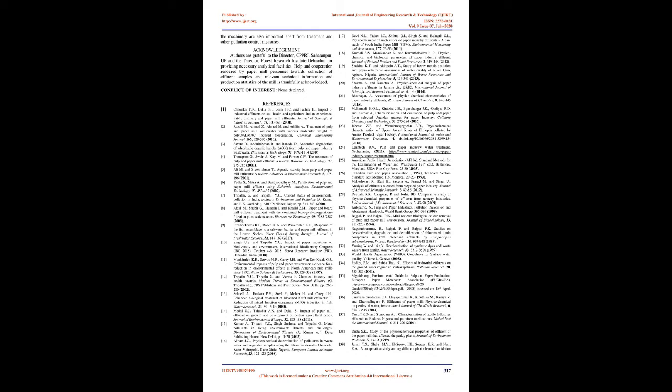The mean value of COD for effluents from all the four units recorded in the range of 881.52 ± 3.19 to 2710.12 ± 4.52 ppm. Highest value of COD was found for the effluent from CE unit, whereas minimum COD value was recorded for C unit effluents, Fig 1. The COD values of effluents from all the four processing units are higher than 350 mg/L, the acceptable limits. 37. This suggested the toxic nature of effluents, which may be due to high chemical concentration along with biologically resistant organic substances. 38.